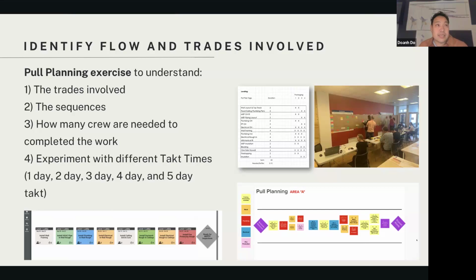But when you're doing something like a museum where it's all open, in that situation it wouldn't make sense to TAKT it because none of the zones would even correlate to anything. Then you would use just the Last Planner System. So there's a whole art and science to when you go towards the Last Planner System side, or when you go towards the TAKT side, or when you have a hybrid between those, right? This is something that you learn to do. Okay, next question is, yeah, okay.